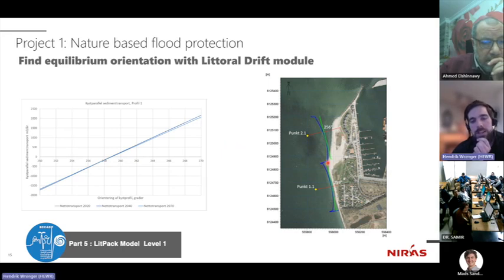Also here you can again see that you start making some simplifications, because when we change the orientation at that profile and rotate it around this point, we're of course going out along the bathymetry lines, and we still assume that this profile will be moved. That's of course the assumption that after we've established this beach, these profile lines will be established as they are here.